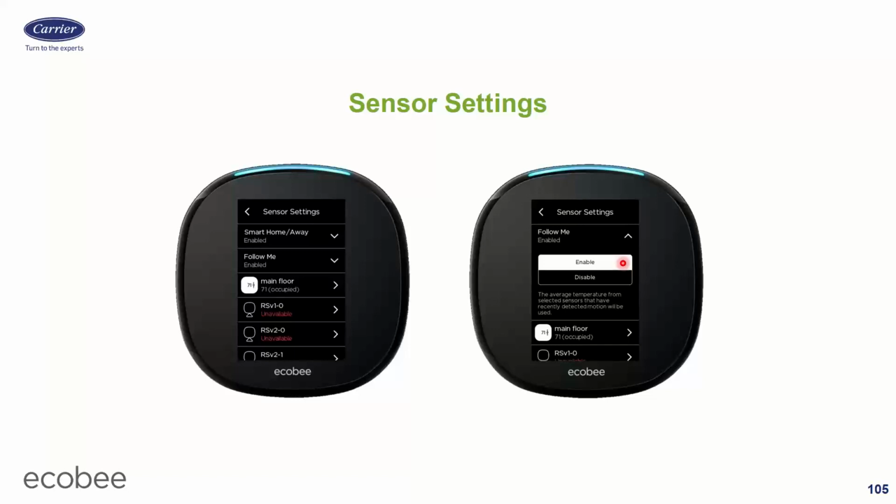But then when you leave downstairs and you go upstairs to go to bed, it'll see that you're up there and that no one's downstairs, and hence it'll control the upstairs, and who cares what happens downstairs. And then if you go to bed, but your wife stays downstairs, it'll see that both sensors are occupied, and it'll average the two in that case. That's what the Follow Me feature does. It averages occupied sensors instead of averaging all sensors.